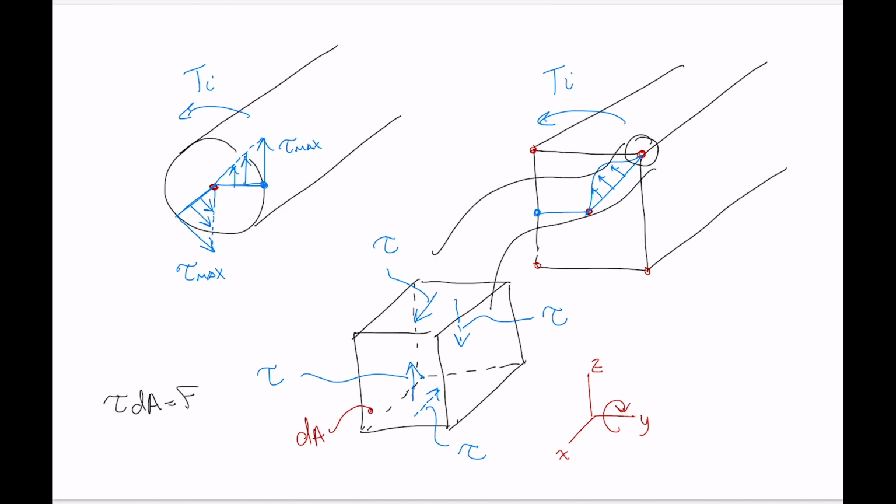The problem here is that the top of this object is just touching air, so there's nothing that can apply a stress there. So on our element, it's this top side that's touching air, and because that's touching air, it means that this shear stress here can't exist because there's nothing to apply it. And if that shear stress there can't exist, neither can that one. And if those two can't exist, neither can these ones. So because of the requirements for static equilibrium, that's actually why that point up in the corner there cannot support any stress.